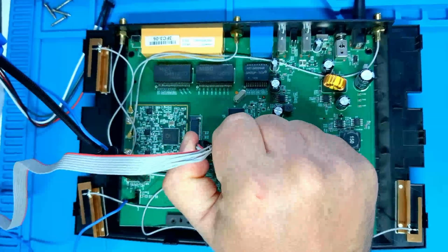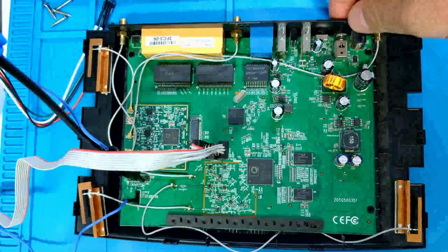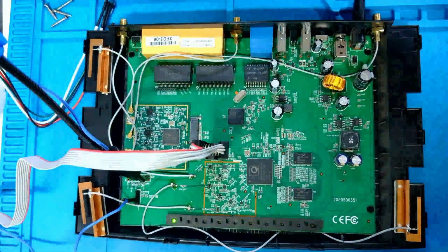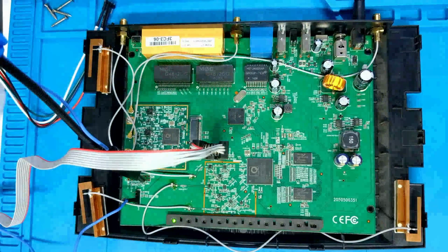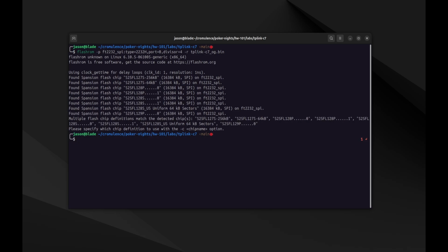Switch this so that we use the target voltage, so we're not powering it. Alright, and then we go back to flash ROM. Alright, so now we can see if we can read from this chip. And what's interesting here is that it's detecting it, it can read from it, and it looks like it's not able to detect just on the ID the exact variant of the chip.